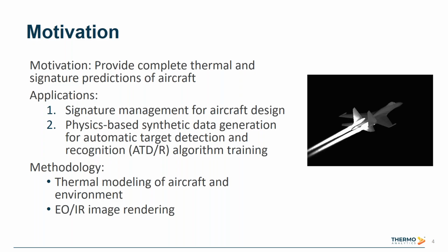Relevant concepts relating to airborne model attribution and creation will be introduced and discussed to provide a groundwork for airborne target modeling. Once that groundwork is set, I will discuss the key aspects that are critical to creating an accurate thermal prediction. In the same respect, care also needs to be taken when setting up and creating 2D sensor renderings in order to produce accurate synthetic IR imagery. Finally, the methodology of airborne target modeling within MuSES will be described with detailed examples.